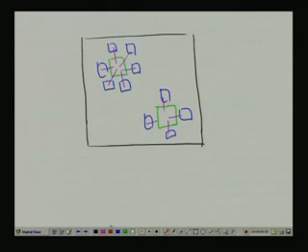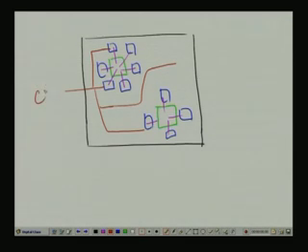Now, say this one needs a clock, if it is a sequential circuit. So, this needs a logic cell clock. Similarly, here these cells also need clocks. So, actually just to avoid the clock skew, because we always prefer the same clock, the clock should be distributed so that the clock skew can be avoided.